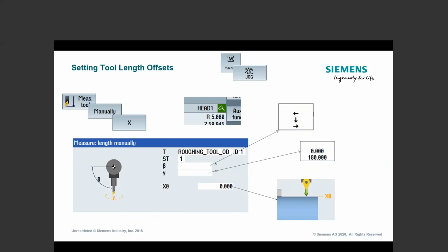You have to make sure that you're using the beta and the gamma to move it around, because once you move the rotary with a direct axis command, like G0 B90, there's no tracking in play. It has to be done with the swivel cycle. But what's happening is that it's automatically inducing our swivel cycle in the background for you, without you having to go to a swivel event and try to turn it on.